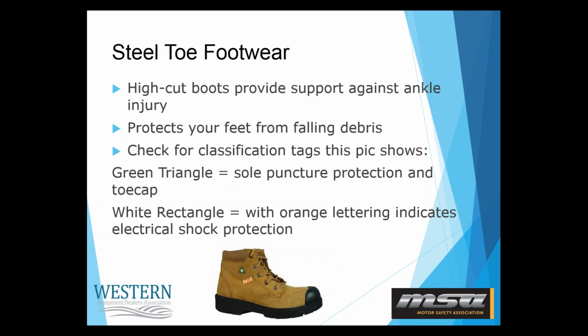Steel toe footwear. Basically, you would lace up the boots such as this type and ensure that they are on snugly. You'd want to store them out of extreme temperatures. As far as maintenance, for some types of shoes there are protective coatings you can put on, and this helps ensure the water resistance, which is critical when it comes to the electrical shock protection that steel toe footwear provides if they have the orange and white lettering. So just ensure that we are trying to keep our footwear dry.